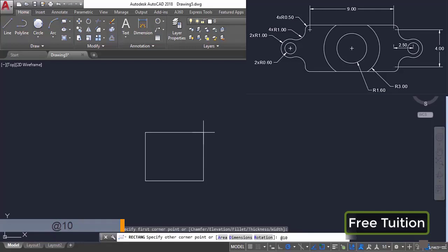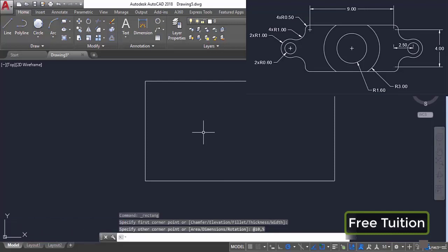So right now you can see in this drawing that the length is 9 units from the first center point of the fillet to the second center point, but the radius of this fillet is 0.5. That means we have 0.5 unit towards left and also 0.5 towards right. That makes a total of 10 units. So that's the length. Similarly, the width is 4 units and 0.5 towards upward and 0.5 towards downward will add up to make it 5 units in length. So I'll type 5 as width. Now here we have it. Now press enter. So that's the rectangle which we need.